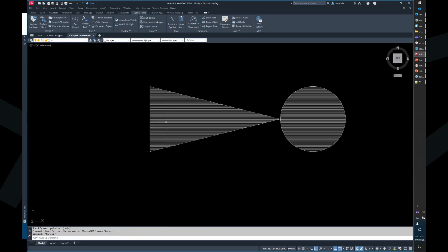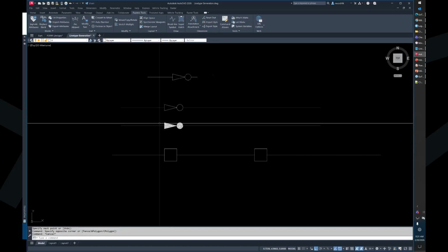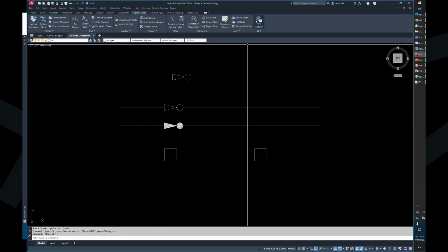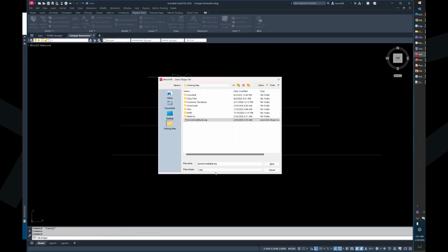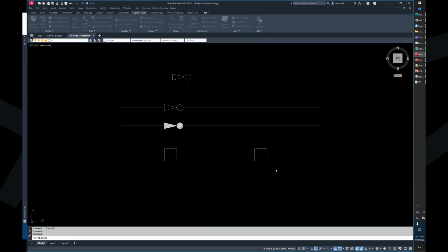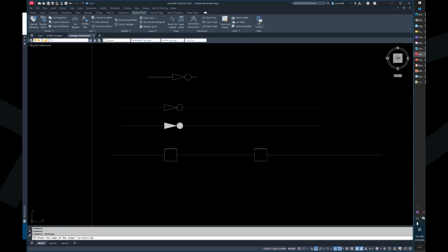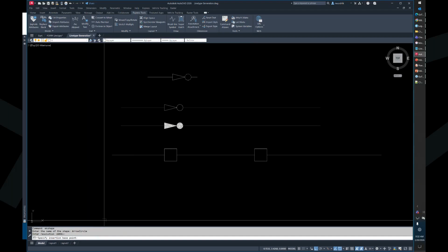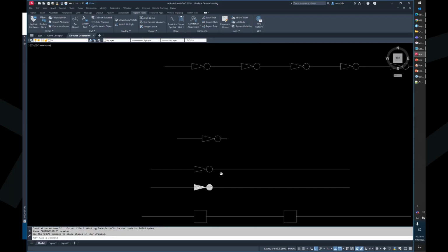Again, this is a very dense arrow. So we'll do the same thing here. Again, come up to tools and we'll make a shape. I'll just call this arrow circle. Enter the name of the shape, arrow circle. Enter the resolution of 4096. Then here's my base point, here's my objects.